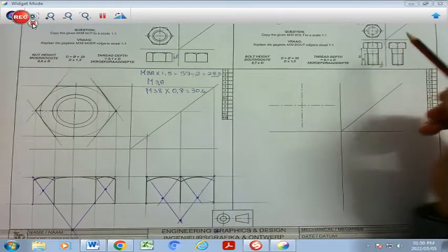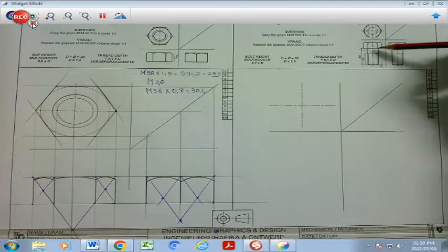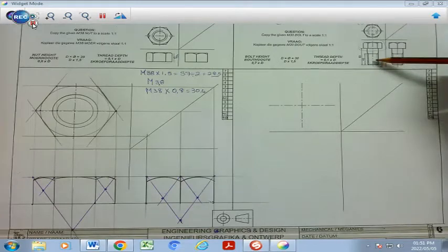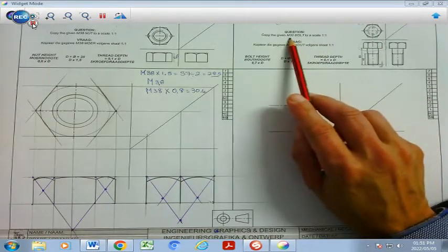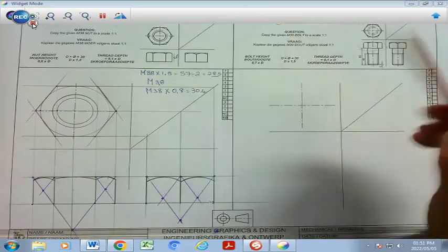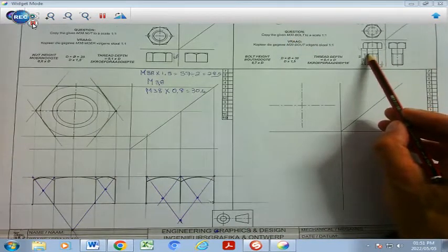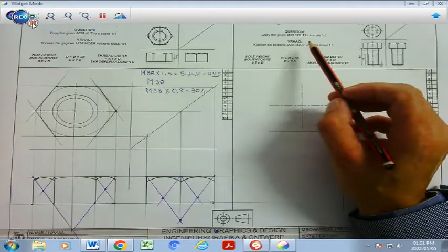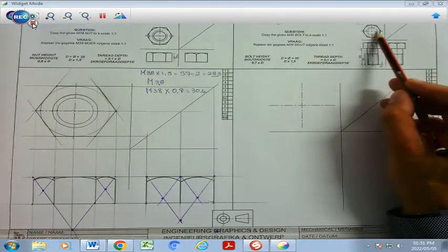of the bolt. The only addition to this would be the body of the bolt, which now consists of a threaded portion and a non-threaded portion. Keep in mind that the metric measurement is 30, and that 30 refers to the body thickness or the body diameter, and it has to be multiplied by 1.5 to get the size of the outer circle.